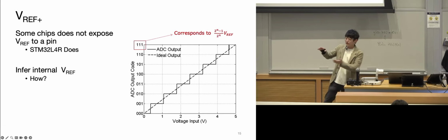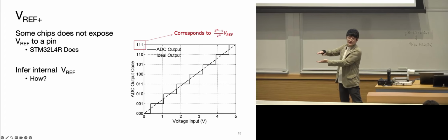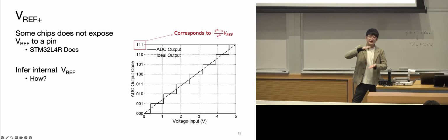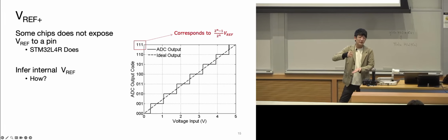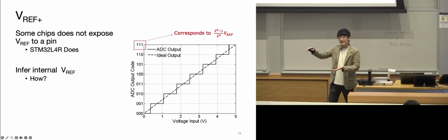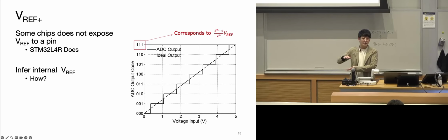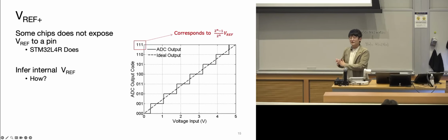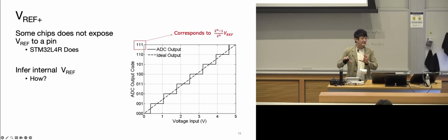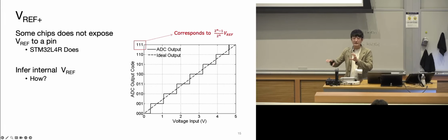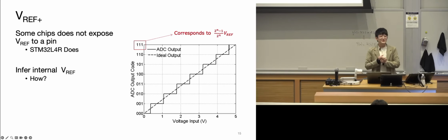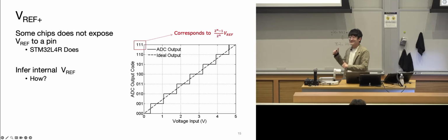You could also keep this 0 to 1 signal, let it go directly into the ADC, but set the ADC's reference to be, say, 1.1 volt or something. This will have a similar effect as the other way, so that you can use the entire 10 bits within that range. So this essentially tells you that you can change how you optimize your ADC sampling at various points on the whole sampling sequence. Was that more clear? Any questions? Okay, cool.